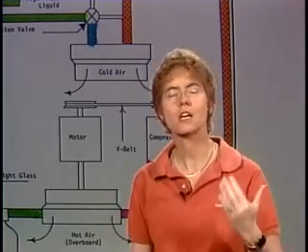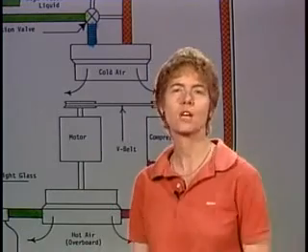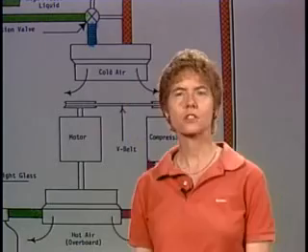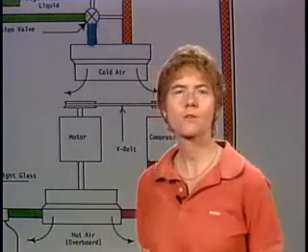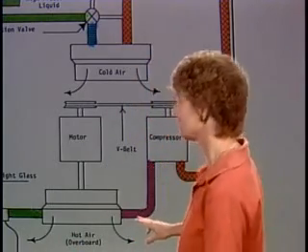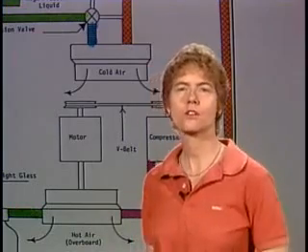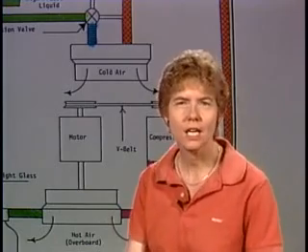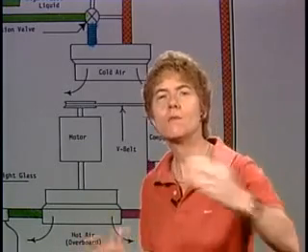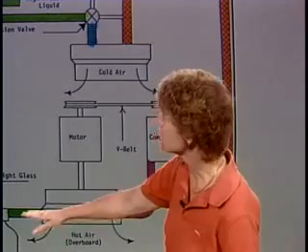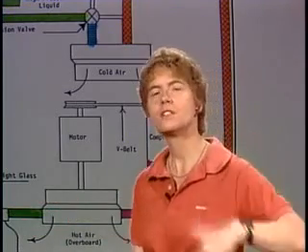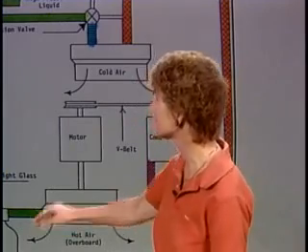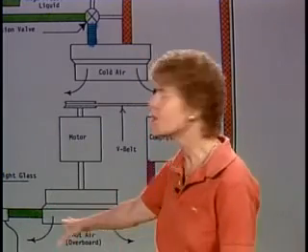So the refrigerant, as it comes into the condenser in a vapor cycle cooling system, is it coming in as a vapor or a liquid? Which one? It's coming in as a vapor, and is it a high pressure or a low pressure vapor? It is a high pressure vapor coming in. And when that refrigerant leaves the condenser, is it a vapor or a liquid then? It goes out as a liquid because it's been cooled off, but is it high or low pressure? It's still high pressure, but it has gone from a vapor to a liquid when it's cooled off going through that condenser.